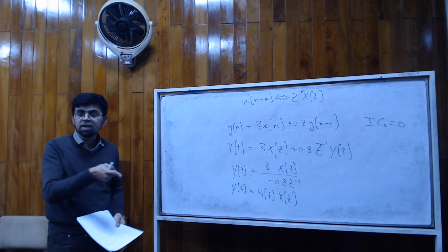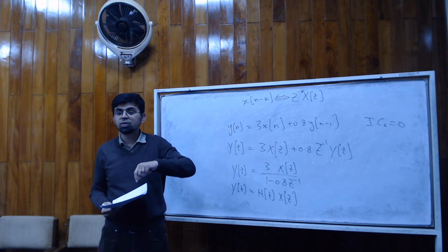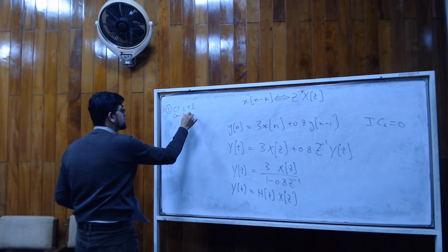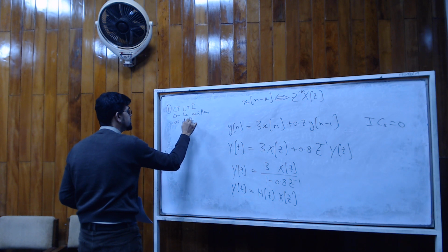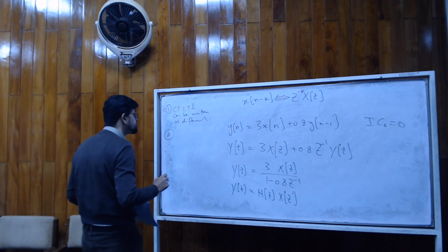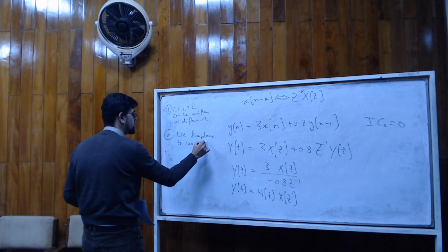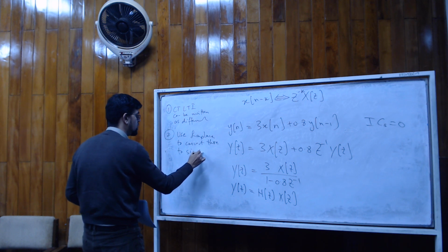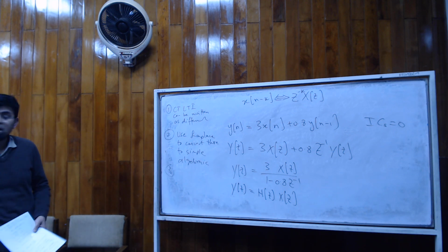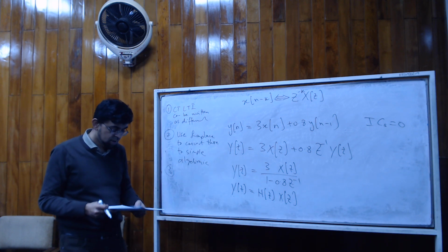Now the same thing happens in continuous time, but with what? Laplace transform. And with difference equation replaced with what? Differential equation. So, firstly, we will say that CT LTI systems can be written as differential equations, okay, which involve differentials of the input and output. That's one thing. Second, using Laplace to convert these to simple algebraic equations. And then third, solve those and do reverse Laplace and get your output. So it's a complete exact counterpart or analogous of this thing. Whatever happened here is going to happen now in discrete time.